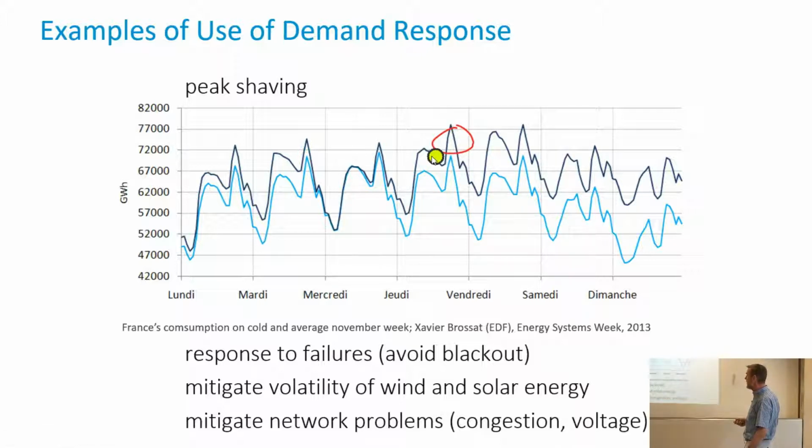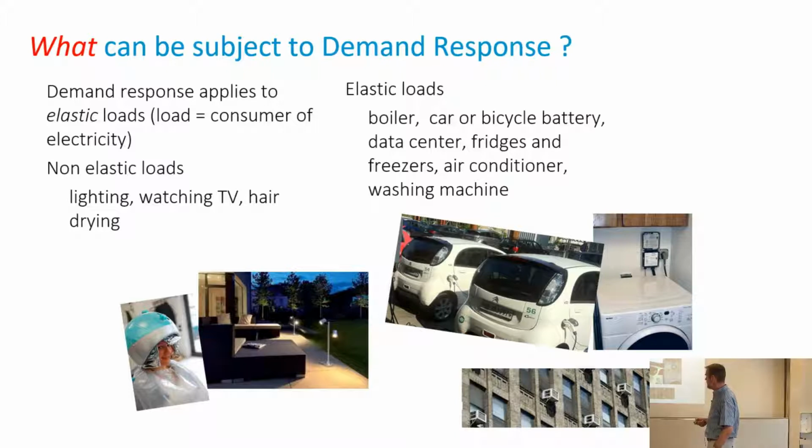An alternative to that is if you can reduce these peaks, which is called peak shaving. Right? So if we can avoid this by, for example, having heating systems that have some inertia, and providing signals to consumers, perhaps via prices, perhaps via other mechanisms, to incentivize people to not use at the peak time here. So peak shaving has been one of the very, very old topics in grid management and one of the incentives and systems that have been deployed early here.